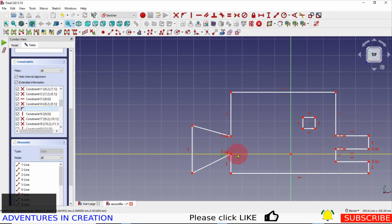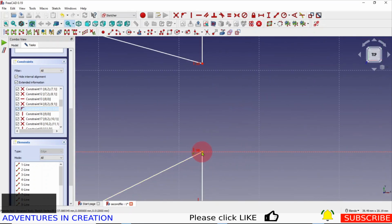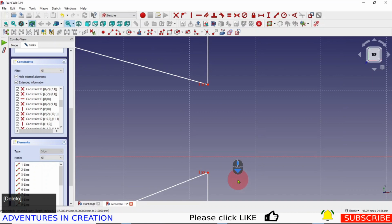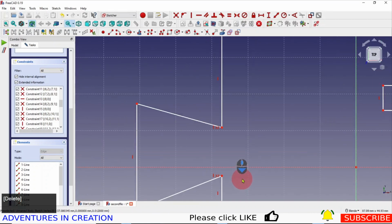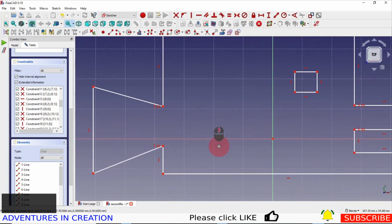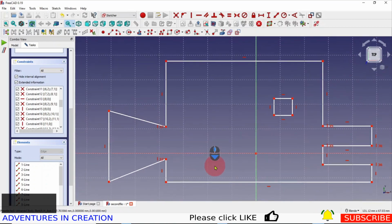And that line has this point affixed to it. So I can highlight that point and say delete. Now I've deleted that constraint. I can take that point and I can move it off that line. So if your points get stuck on a line, it's typically because there's a constraint that's holding it there. And so remember that if you want to move it off there, you certainly can do that.